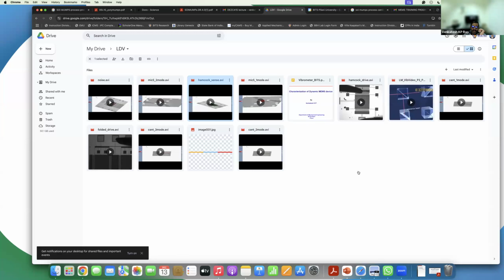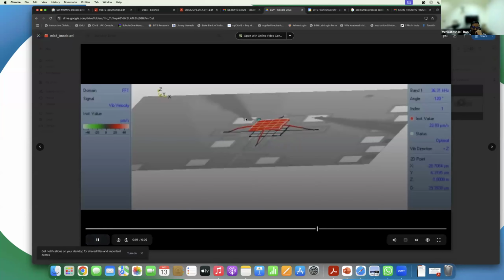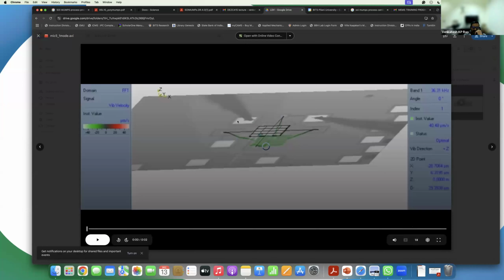Now, I told you that it's not just the accelerometers and gyros. You can even realize microphones, right? So look at this. This was the case of a microphone, where we actuated with the help of two probes. So there was an electric field. Then the structure started to vibrate in the up and down motion. That's what you basically saw.